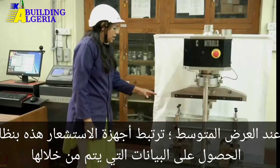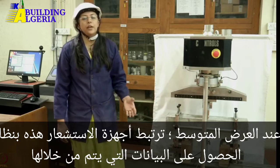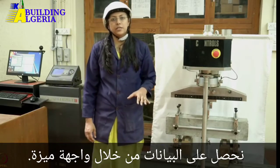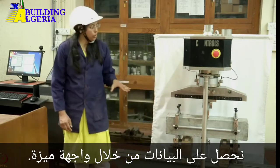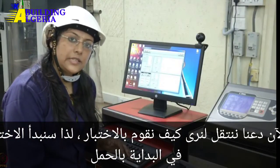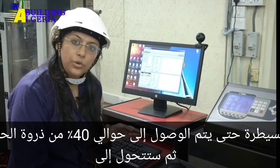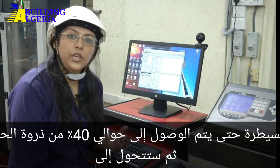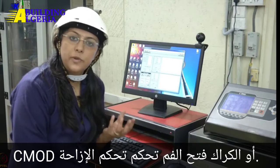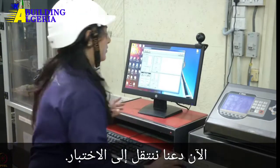These sensors are connected to the data acquisition system through which we acquire data through our advanced interface. Now let's move on to see how we do the testing. Initially we will start the test with load control till around 40% of the peak load is reached, and then we will shift on to the CMOD or crack mouth opening displacement control. Now let's move on to the test.